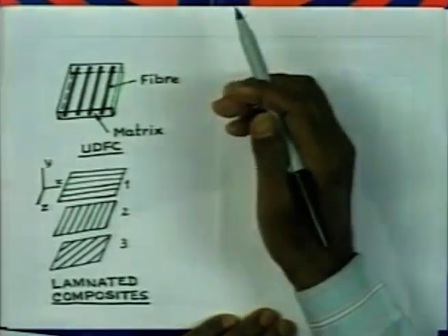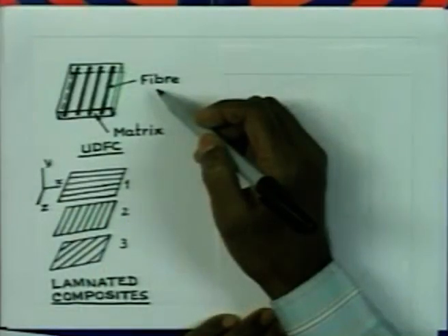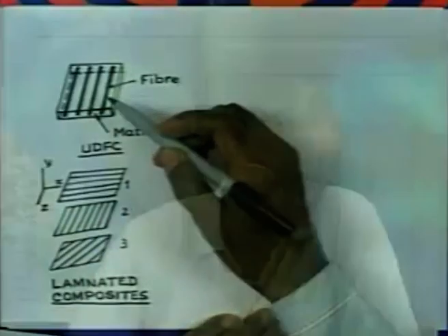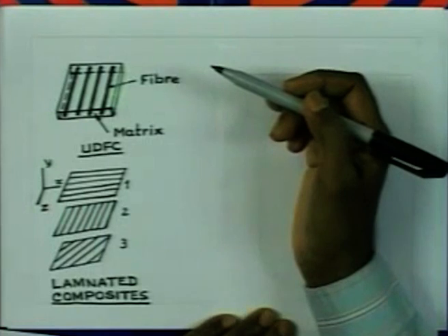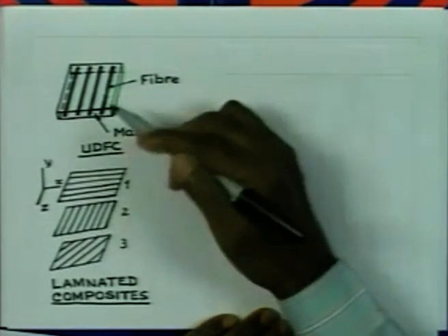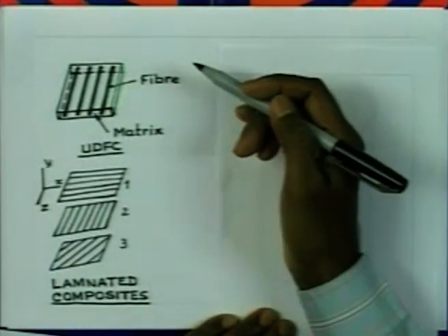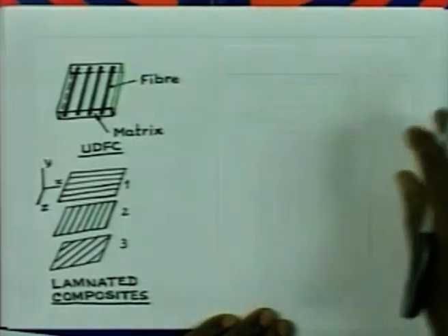They have material constants like one modulus in this direction, another modulus in the perpendicular direction. They have one Poisson's ratio constant relating the two directions, and also one modulus of rigidity in the plane of the material. So, therefore, there are four independent elastic constants. If this system was isotropic, then you would have had only two material constants.